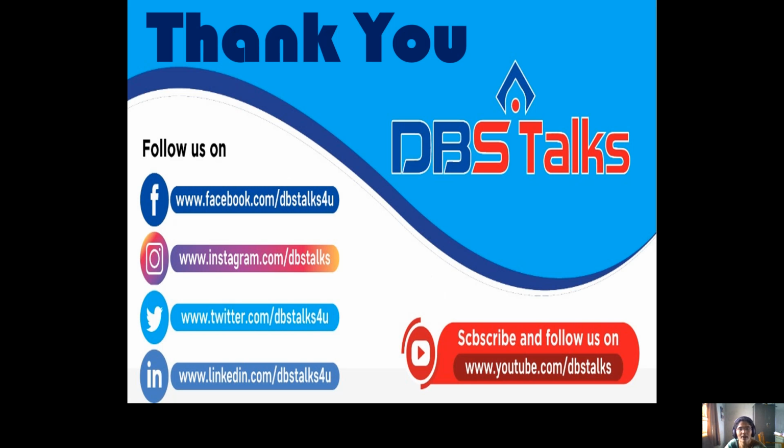Okay, so now in this class we discussed the power output drawn from the driving axis, specific energy consumption, and what the factors are. The main factors which are affecting the specific energy consumption, and finally we discussed some of the important definitions. Those are adhesive weight, dead weight, accelerating weight, and coefficient of adhesion, and you have to see the problem. Okay, thank you.